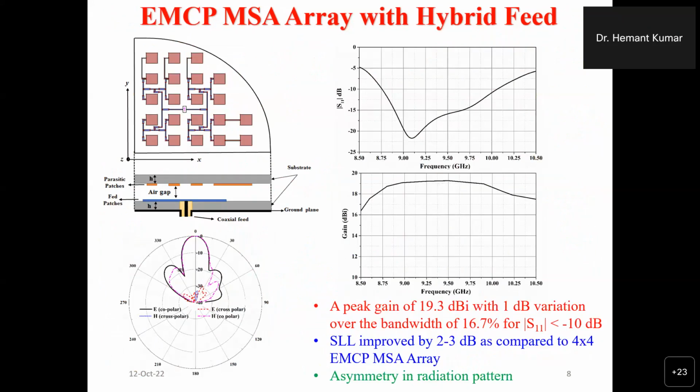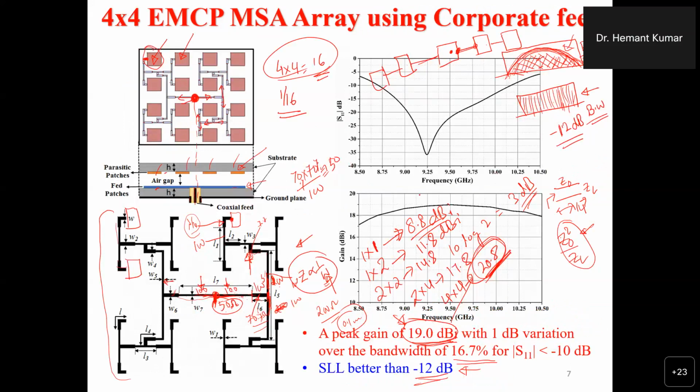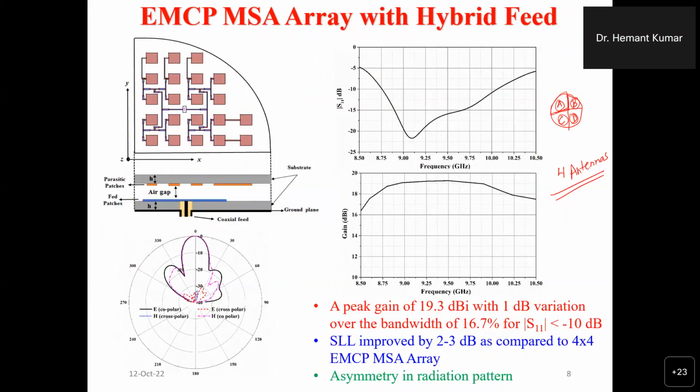Then, we are going to use four similar antennas in our monopulse antenna, and we are going to use a circular structure. Basically, one quarter of the circle will act as one antenna, another quarter of the circle will be another antenna, and like this we will form a circle. So four antennas: one is A, another B, C, and D. The 4x4 network that we designed is rectangular in shape, but we want the shape of the antenna to be one quarter of the circle. So we wanted some shape like this.